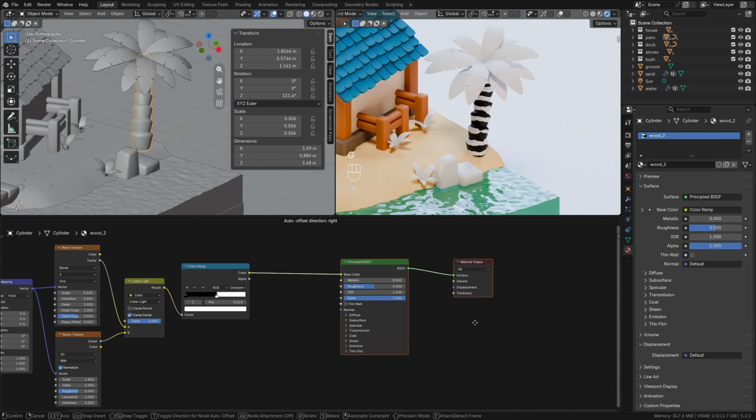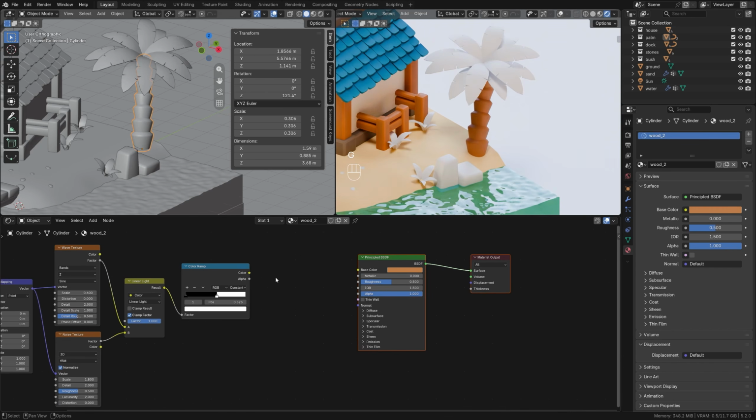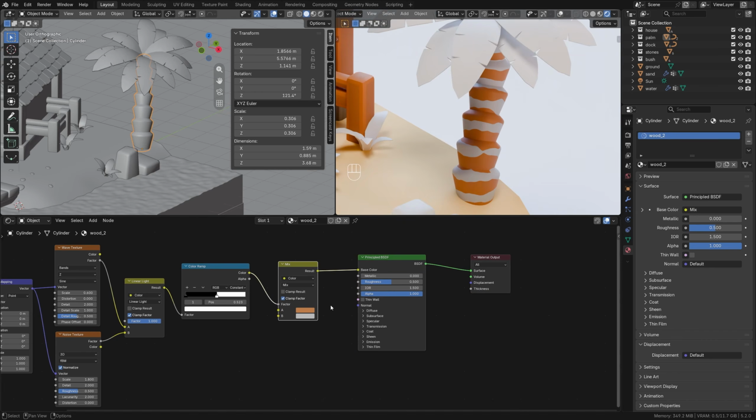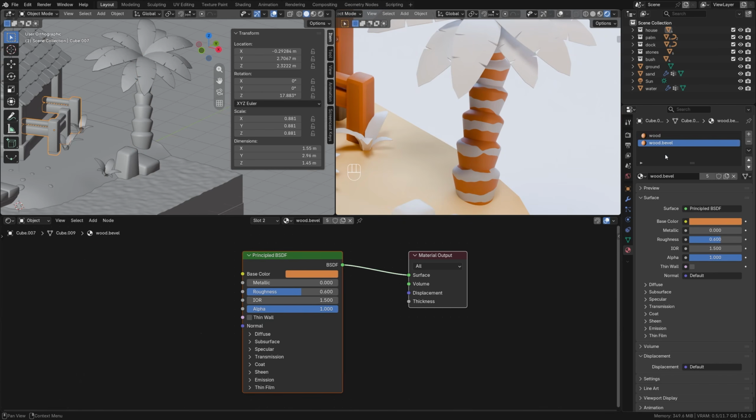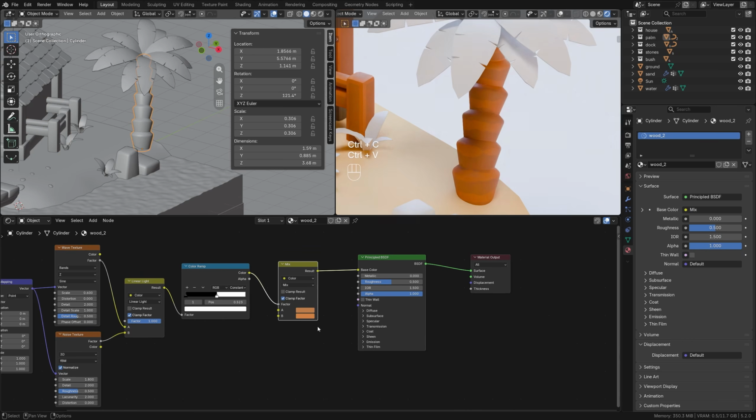And right now for us, we simply need to restore our colors. Again, we take one more Mix Color node. This color we will copy here, plug in as factor. And now for us, both colors mix, and we can from here already copy the second color, again via Ctrl+C, and here via Ctrl+V paste it, so as not to set up a new.